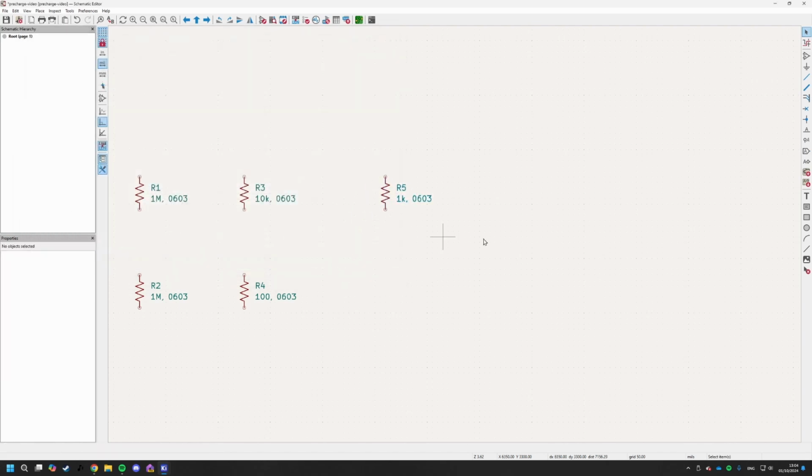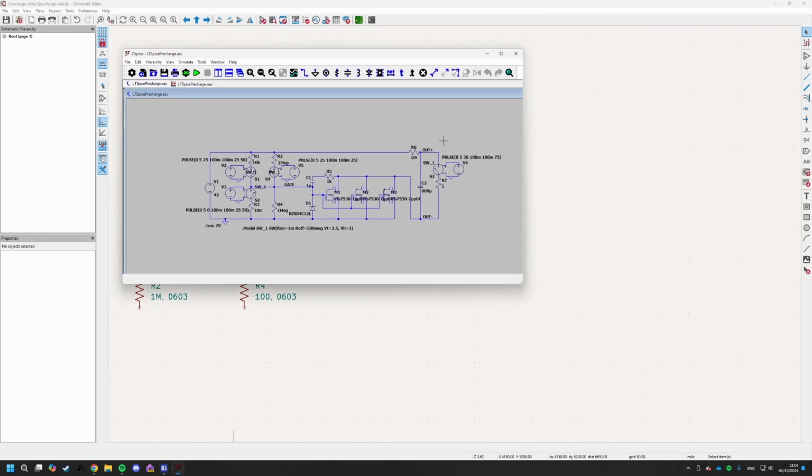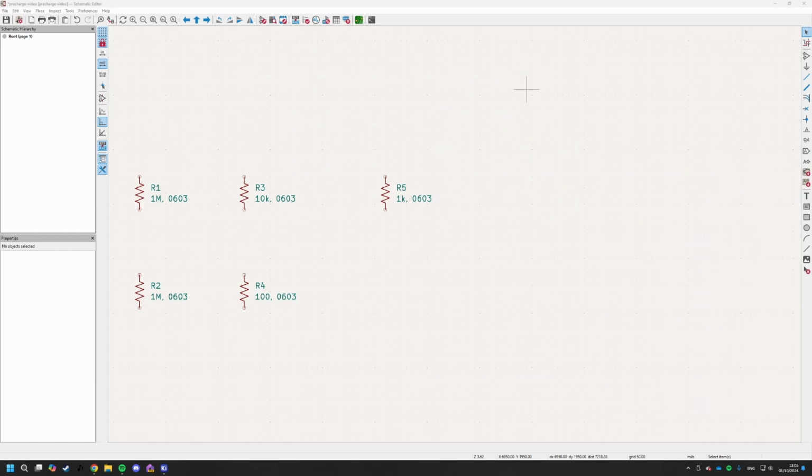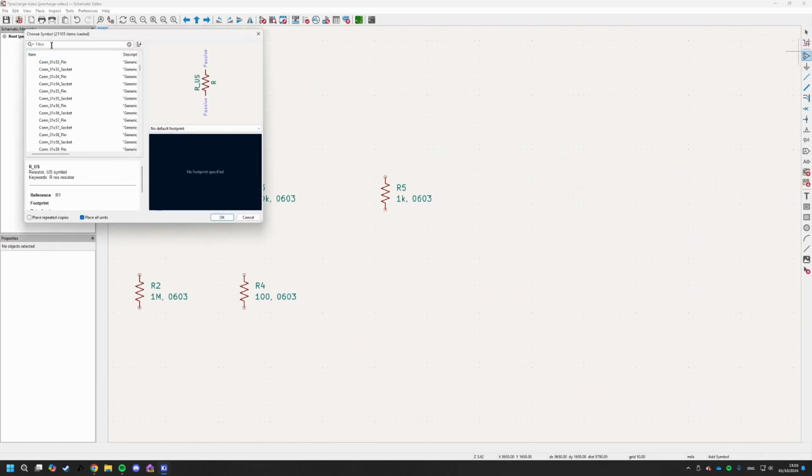Cool. Now, we would also like to have a capacitor for our timing circuit, which, let me bring it up real quickly. So right now we placed these four and this resistor. Now let's plop down this capacitor. So let's go back into the symbols, type in capacitor. It will not be polarized for our own convenience. So let's go ahead and plop this one down.